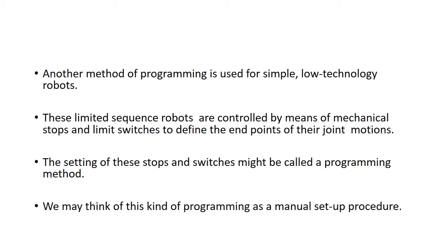Another method of programming is used for simple, low-technology robots. These limited sequence robots are controlled by means of mechanical stops and limit switches to define the endpoints of their joint motions. The setting of these stops and switches might be called a programming method. We may think of this kind of programming as a manual setup procedure.